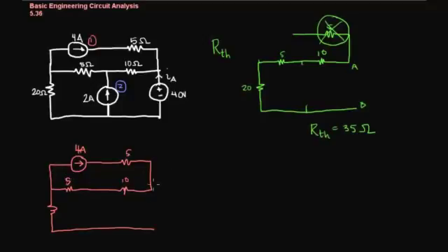And what we want to do is just go ahead and use the polarity assigned by the battery. Okay, so even though typically we would think of this as being a load on the circuit, it's actually going to be providing power to the circuit. Okay, so we'll use the polarity of the battery just like that. And that's what we're going to call V prime on the open circuit.